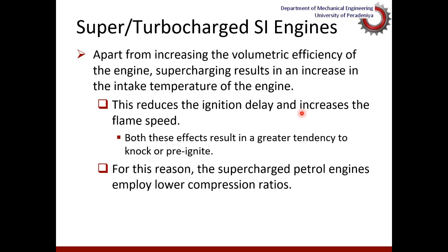However, with this intercooling, as we know, that tendency could be reduced to a great extent, and also certain supercharged or turbocharged spark ignition engines operate at a lower compression ratio. Therefore, you could reduce the tendency for knocking.